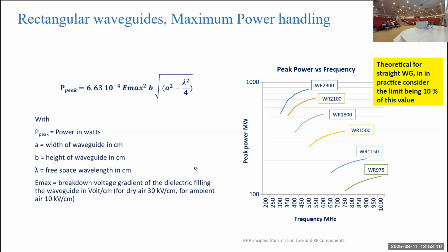All of the RF power would be wasted into free space. You have to direct it to the particular point where you want to use it. If you want to accelerate the electrons, you need an accelerator with RF fields inside it. The higher the field gradient in the accelerating structure, the more power you can gain. The optimum is a rectangular waveguide, and its size depends upon the frequency.